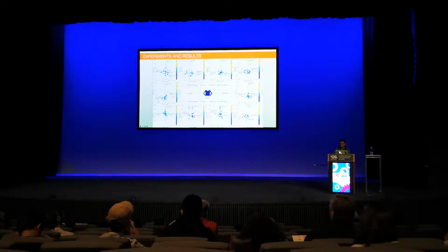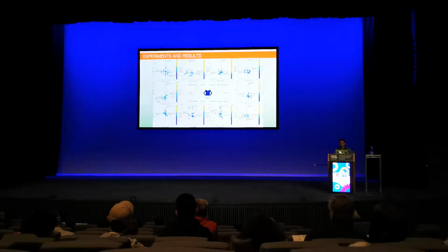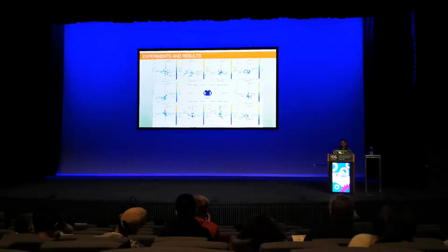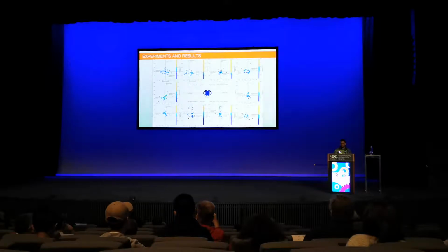So in general, the results of the walk kick were very stable, regardless of the type of kick direction, with only 2 out of 300 kicks that resulted in a fall. So 1 right front kick and 1 right back kick resulted in a fall, which is less than 1%. The intended ball direction was consistent, with an average absolute bearing error of less than 6 degrees, which shows that the walk is able to kick in any direction relatively accurately while the robot is walking.